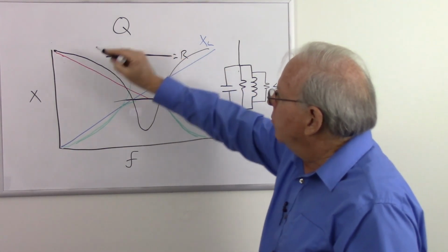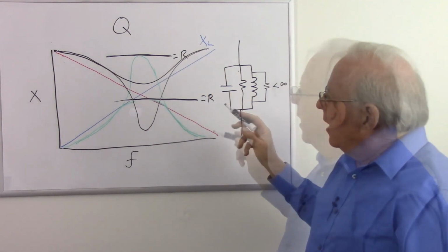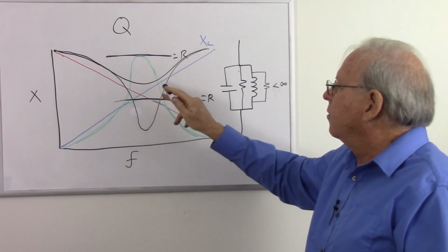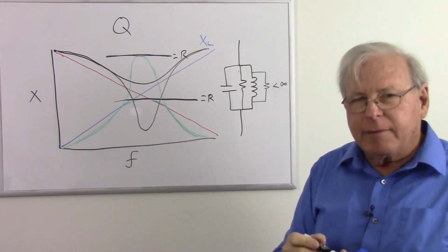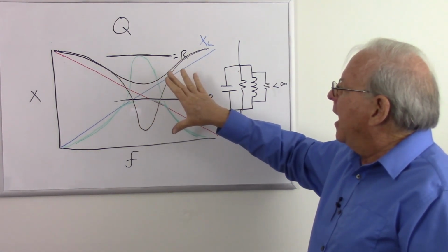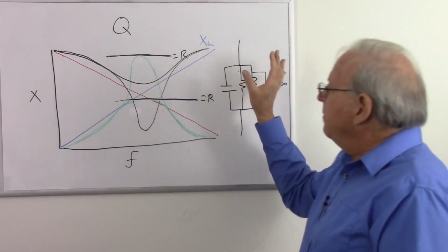And if I have a low Q, the current is going to go something more like this. And so the current kind of does the opposite of the voltage. It starts high and goes low and then goes back high again. And so we can manipulate how this circuit works as a frequency filter by whether we're interested in the current or the voltage. Let me illustrate what I mean.